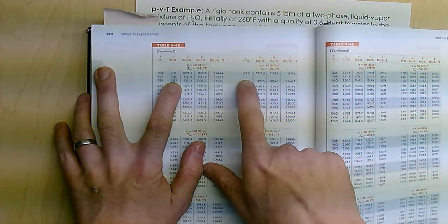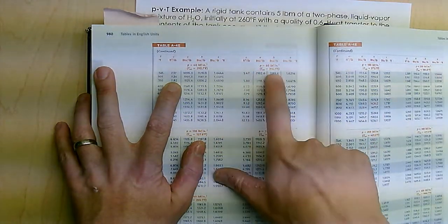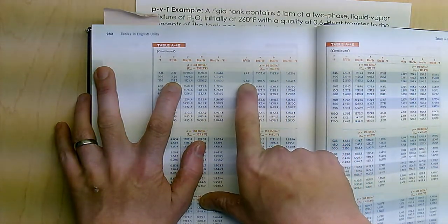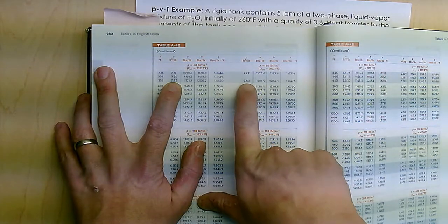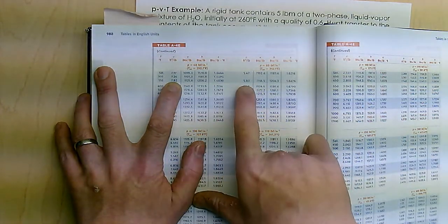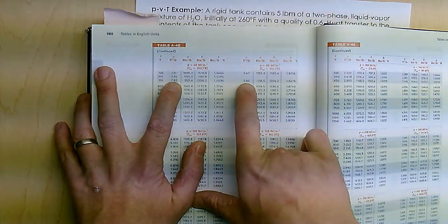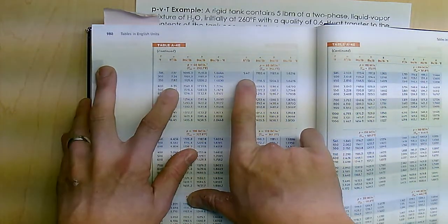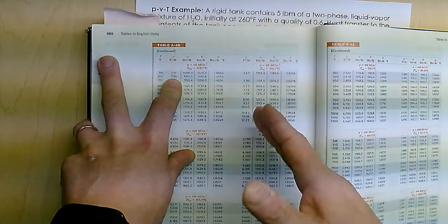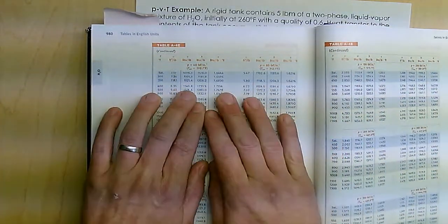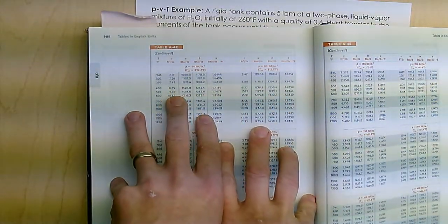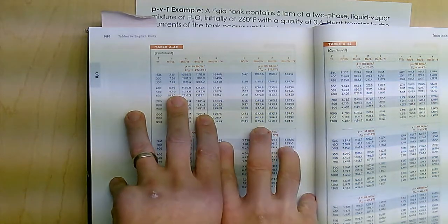And then between saturation, which for 80 psi is 312, I have a volume in between there. That's going to be at 320, I don't know, 5.5. So you can see I'm somewhere between 7.5 and 5.5, which is where I am. I'm at 7.07. So unfortunately, I have to do a double interpolation, which is more than we typically would have to do on our problems.